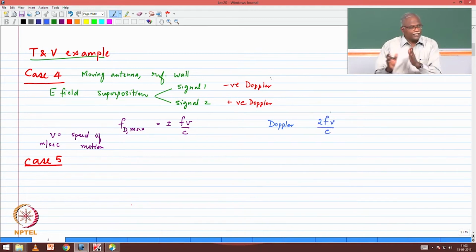So in terms of the spectrum shifting, the spectrum can shift all the way to the left because of the negative Doppler, or all the way to the right with positive Doppler. When you have a large number of Doppler components arriving, give me a spectral interpretation. What does your received spectrum look like? In the case of an AWGN channel, it would be a fixed one. Now there is a smearing of your spectrum because some Doppler components are shifting to the left because of negative Doppler, some are shifting to the right, and there is the resultant.